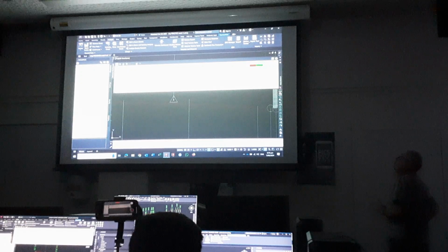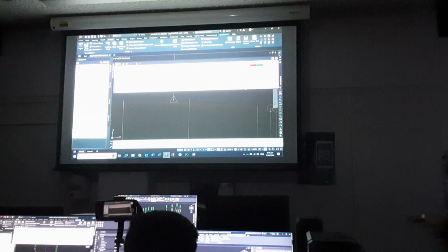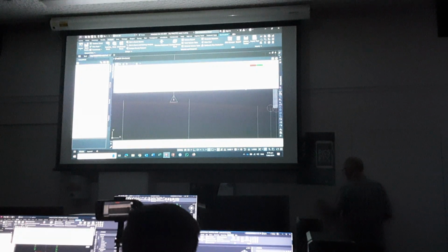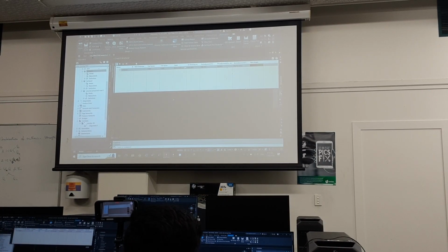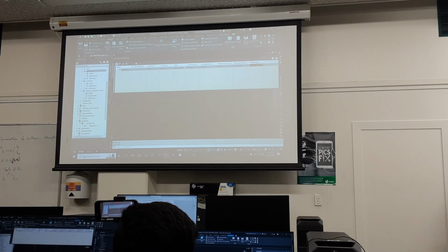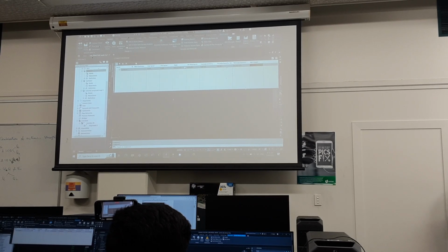Now, one other thing you need to be aware of is we're not taking into account any compaction or expansion, so we're just using a cut factor and fill factor of 1, and that is quite important to the process. You need to talk to your geotech engineer who would tell you those numbers. You might remember in your civil engineering notes, the geotechnical engineer is the kind of dude that comes along and tells us the compaction factor of some of these materials. In other words, if you can compact it down, your balance will be quite different.